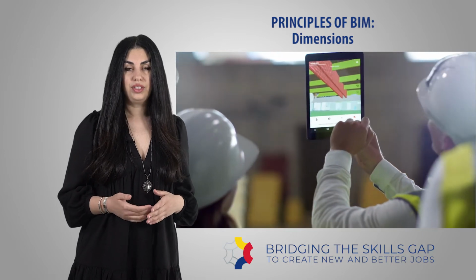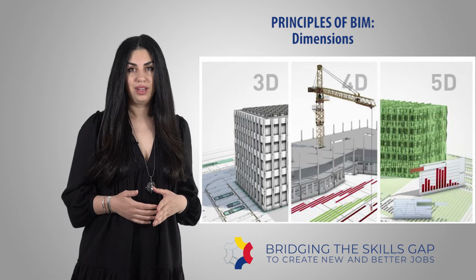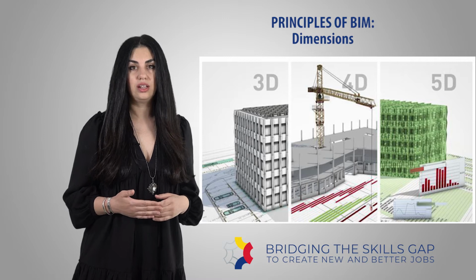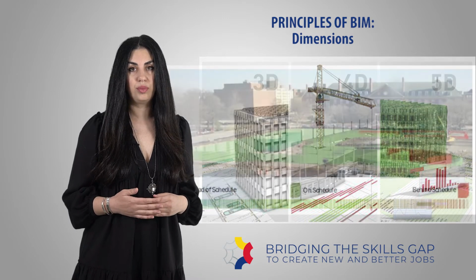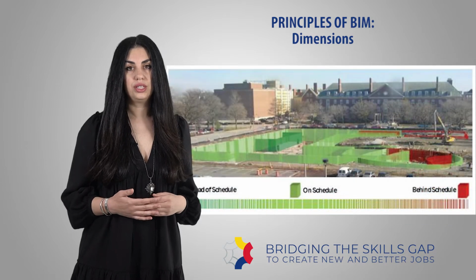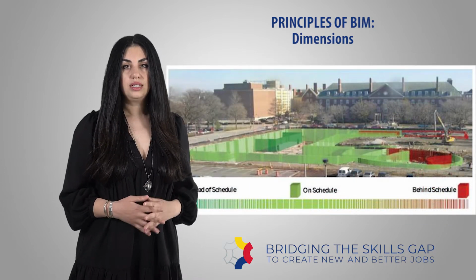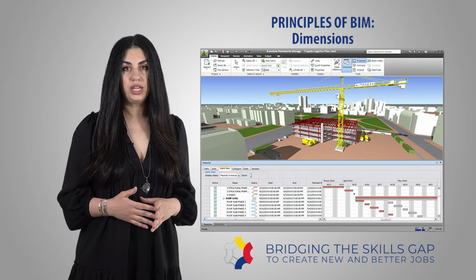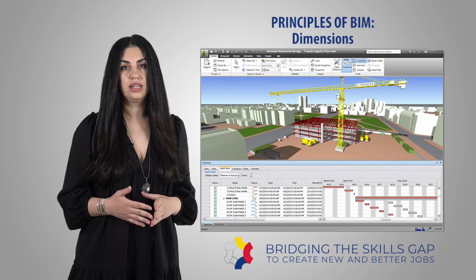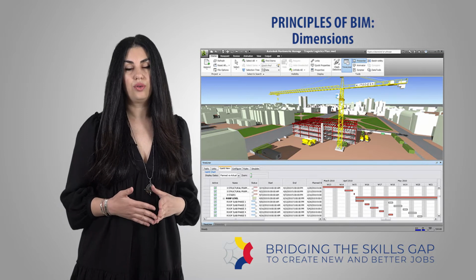Then comes the 5D, the cost dimension. Added to the fourth dimension, it allows the stakeholders to keep track and analyze cost and budget over the construction and the life cycle. This includes capital costs during construction associated to running costs and the cost of the renewal or replacement.